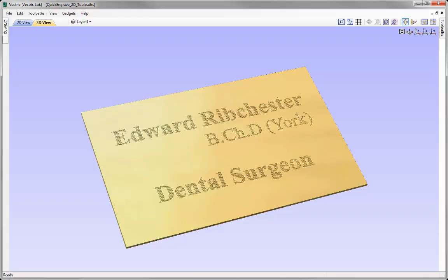In this example, we take a look at the Quick Engrave toolpath whilst using some specialist tools which are spring-loaded so that they can engrave over uneven surfaces. We also take a look at its drawbacks of not being able to specify exact cutting depths, and then ways in which we can encourage more cut depth by applying more pressure to the tool.